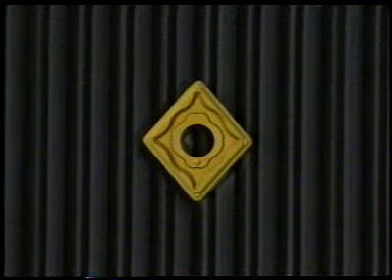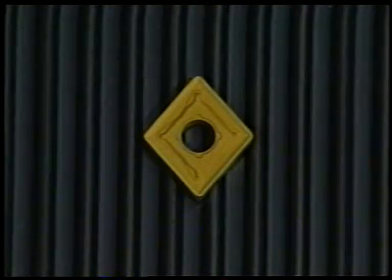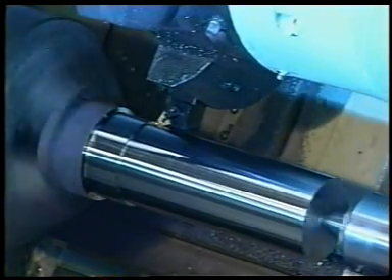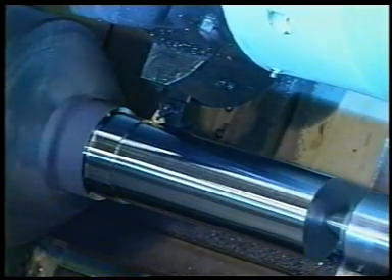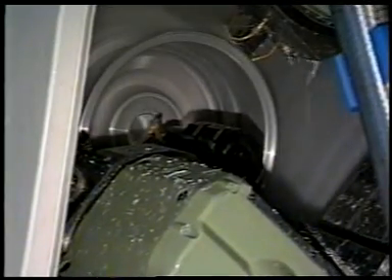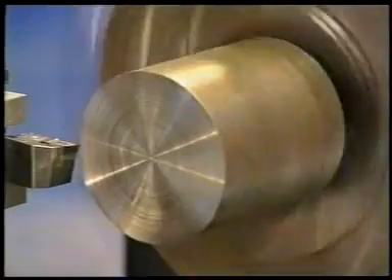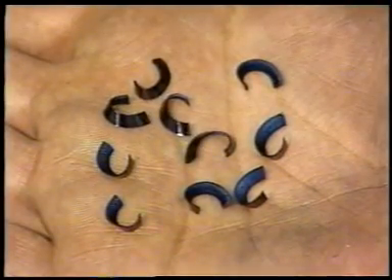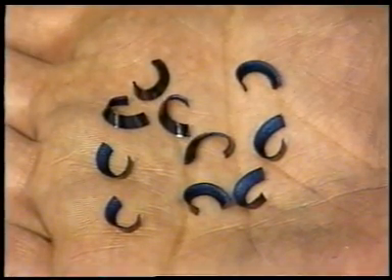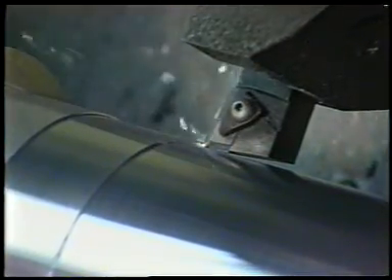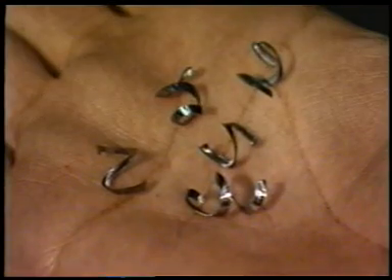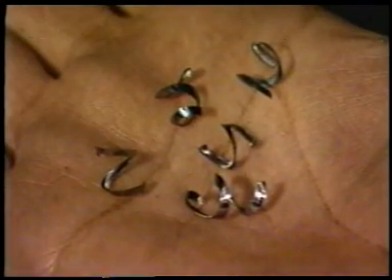Grooves, bumps, waves, dimples, and all sorts of shapes have been designed into cutting tools. Chip breaker geometries are all designed to work at designated feed rates and depth of cut. High-pressure coolant effectively promotes chip breaking if all else fails. There are 4 basic chip types in turning. Chips that resemble small 6s or 9s are the ideal type of chip. They are easiest to dispose of and are made in turning when tools are cutting most efficiently. The helical chip is acceptable if small enough.